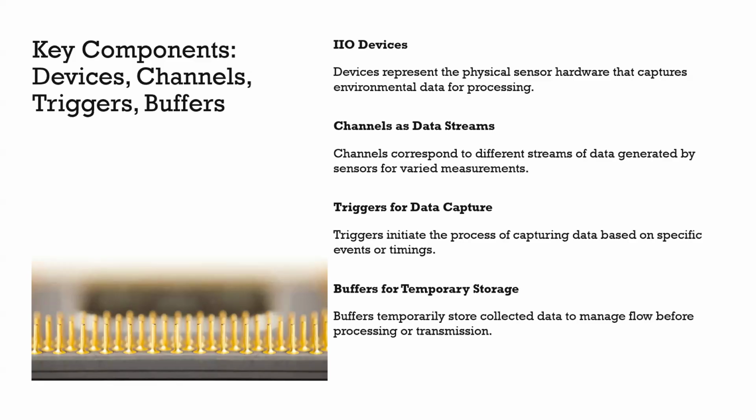This trigger can be any interrupt, a hardware interrupt or a software interrupt. These are features within the subsystem designed to capture hardware-triggered or software-triggered interrupts. In a traditional Linux driver, we have to write all this trigger handling on our own.